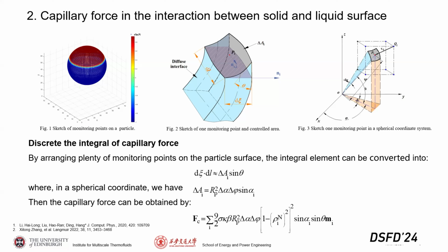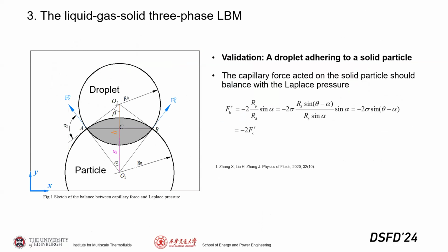By this, we developed the model of the capillary force, and based on this, we developed the lattice Boltzmann method to compute this three-phase flow. For the multi-phase flow of the fluid part, we can use the phase field model or color gradient model.